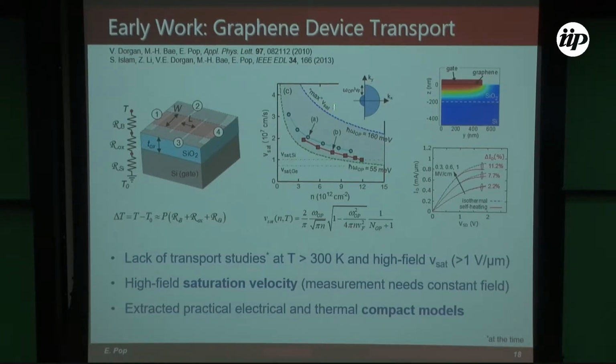And this is what the population of forward moving and backward moving electronic states, or hole states, because it's the same thing really, look like in graphene. But the good news is that these numbers are bigger than the saturation velocity in silicon. So if you want to make good high-speed transistors where you don't care about turning them off, this is good news. Mostly good news.